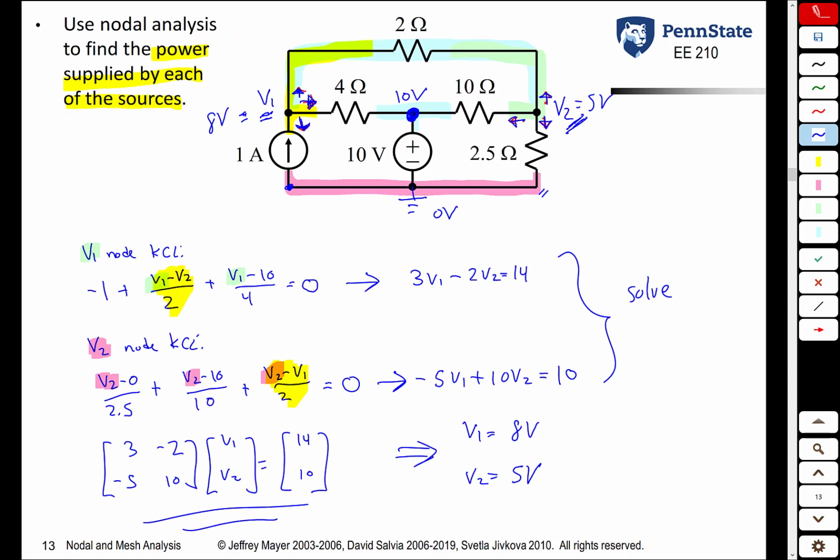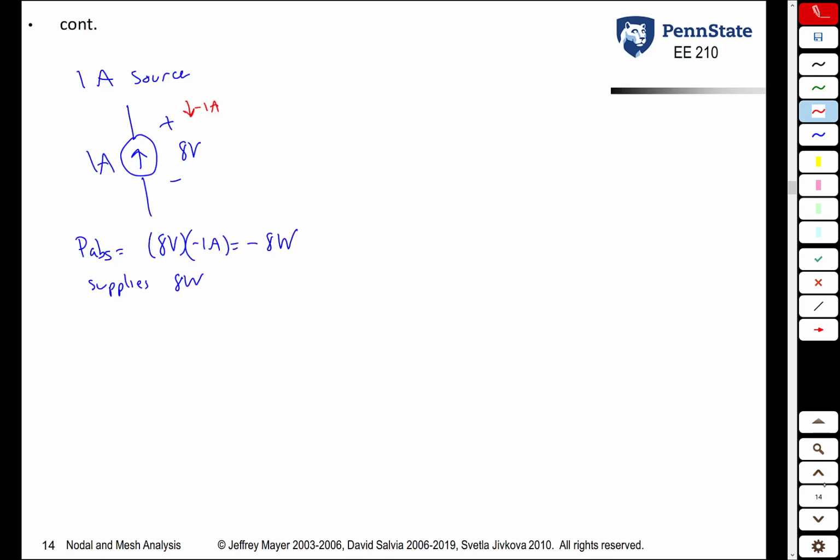So what we're going to do now is a KCL equation right here. Notice we did not do KCL there before. We did KCL at this node, and we did KCL at this node. We did not do KCL in this middle node. The only time you ever do a KCL equation on a node connected to a voltage source is to find the current into that source, and you do that only after you know all the voltages in the circuit. At this point, we know all the voltages in the circuit, so now and only now we could write a KCL equation at that blue node.